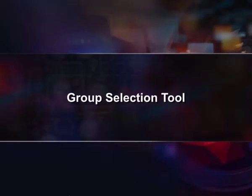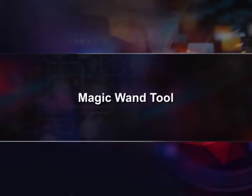Group Selection Tool. Selects a group of points all at once, such as the 4 points of a rectangle. Magic Wand Tool. Selects all objects in a document with the same or similar fill color, stroke weight, stroke color, opacity or blending mode. By specifying the color range tolerance, you can control what the Magic Wand tool selects. Lasso Tool. Selects objects, anchor points or path segments by being dragged around all or part of the object.